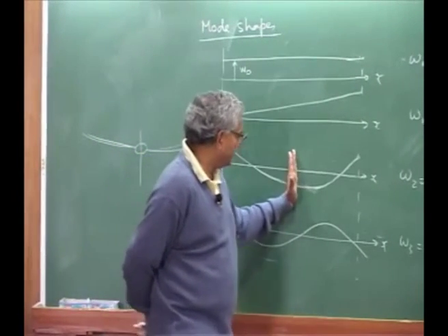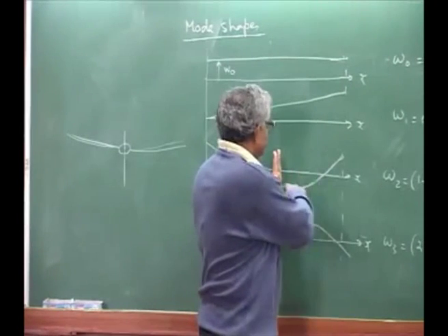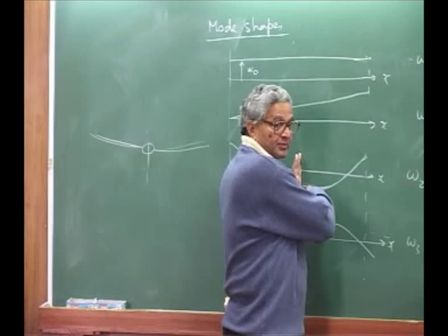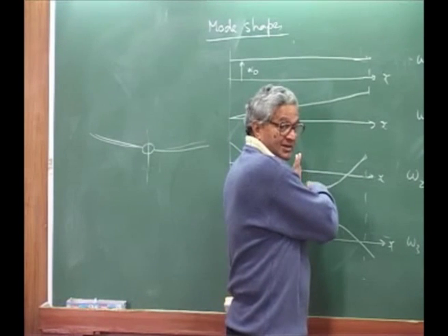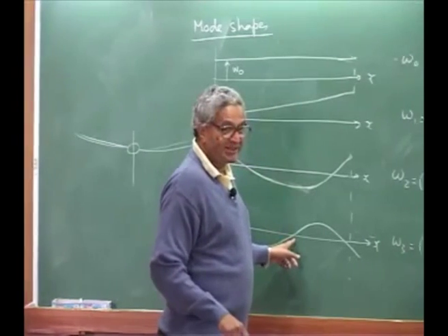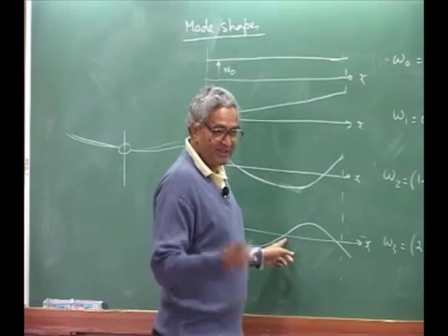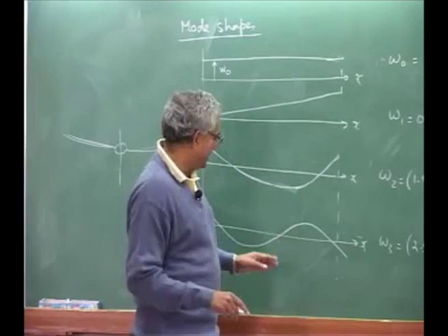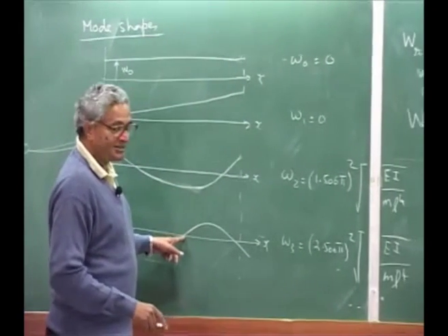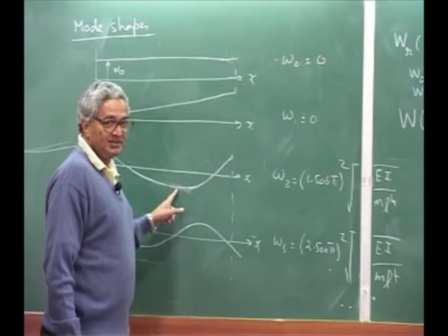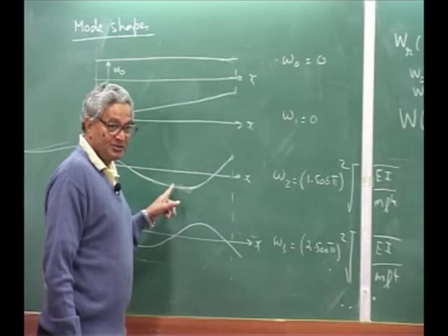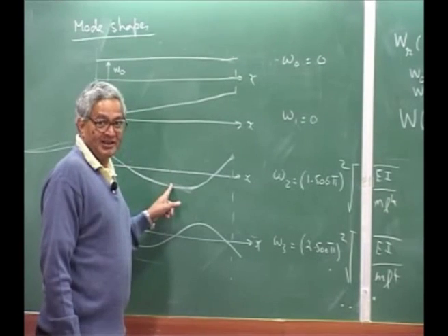If I say this half, slope is 0, and then here curvature you set, displacement I allow, okay. Whereas here you have to take the other way around, displacement is 0, and here curvature is 0, here curvature exists. So you have to put curvature, second derivative, you cannot set it 0 here, okay.